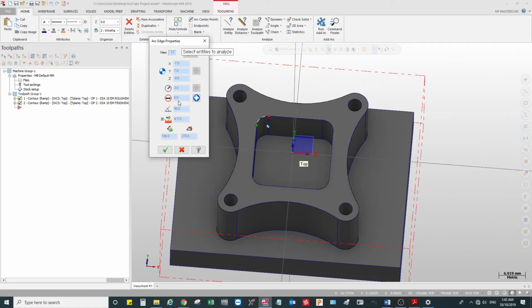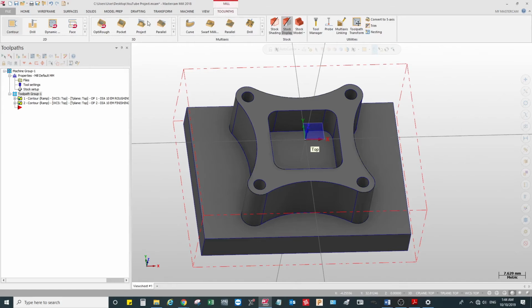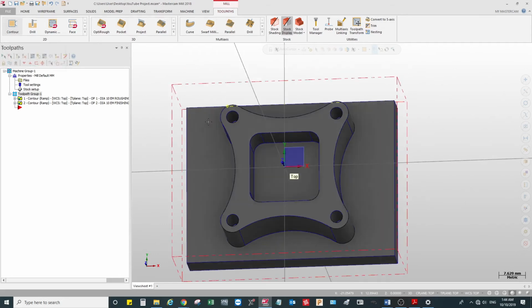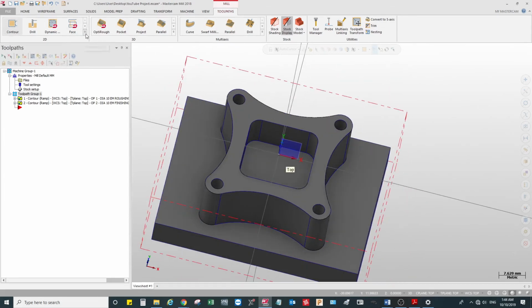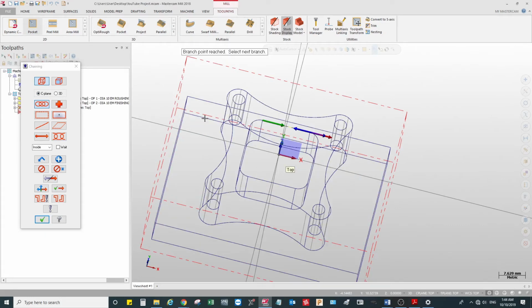I'm going to click on toggle display on selected operation. Once I click it off, I can only see the second operation's toolpath. So now I can see how the second output looks, and see the lines, and it's taking a 0.8 cut, and I can see in the back plot how it's going to machine. Okay, so all good.